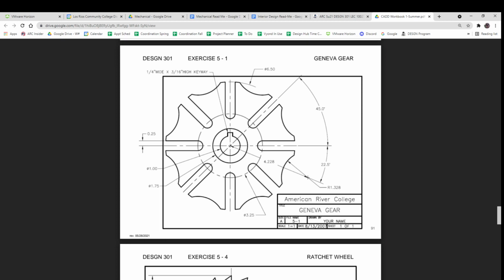But key stock is so simple, and you would just use a key cutter or a broach or something like that, or an EDM cutter. Just ponk, and you do it, and then you drop a piece of key stock in. If there's not a lot of power, you don't have a lot of stress at this little interface.